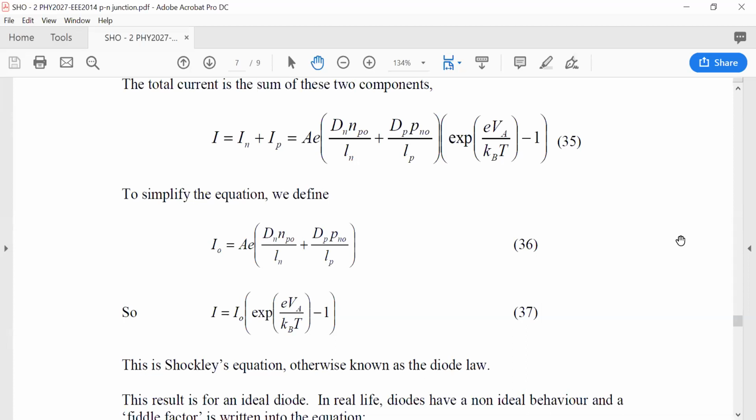We also derived the Shockley equation, which is shown here. And we showed that we can quantify the amount of current flow I with respect to voltage V across the junction from knowing the material parameters, the device dimensions and the doping concentration. And we did this by showing that the devices are minority carrier devices, as it's the diffusion current that determines the current flow through the device. And we therefore needed to calculate the minority carrier concentration, as it's the gradient of the minority carriers that determines the diffusion current and consequently the current flow through the PN diode.